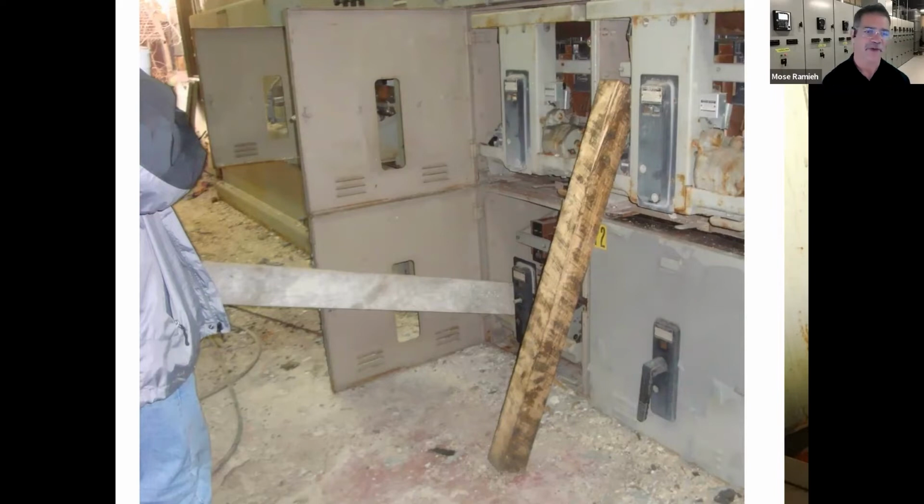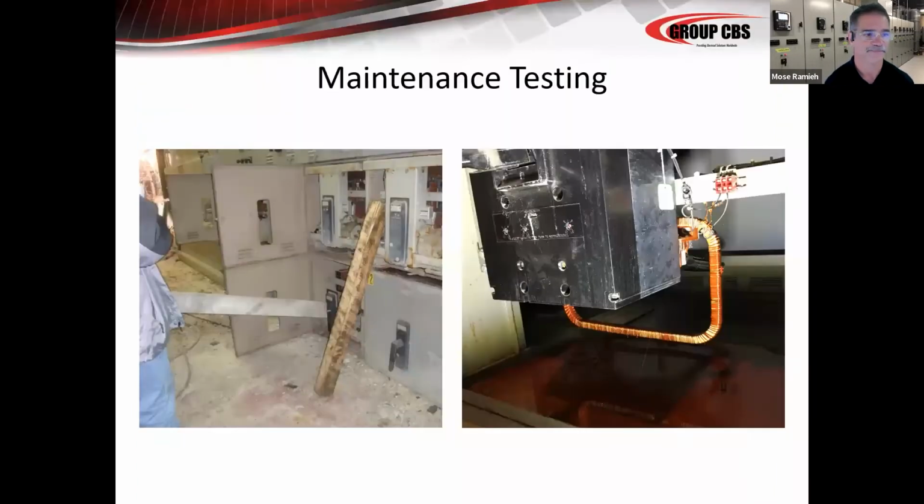And so once again, backing up, if this breaker can't trip, then any arc flash study that's been conducted of the devices downstream is completely invalid. There is no way that the breaker can trip, which means if there were to be a fault downstream, it's going to be much more catastrophic than the arc flash labeling, the arc flash study, would predict. So once again, I know this is a graphic illustration of a problem, but it does happen.